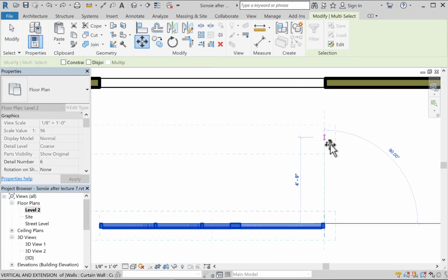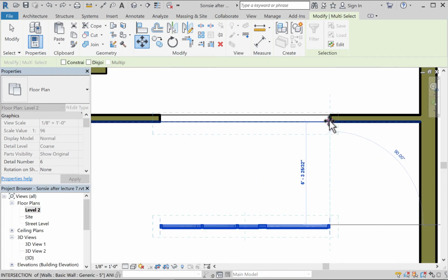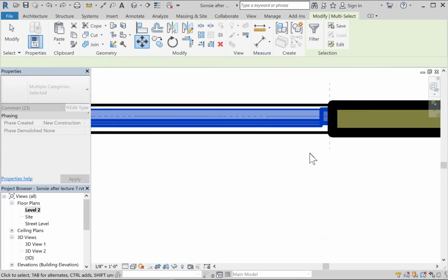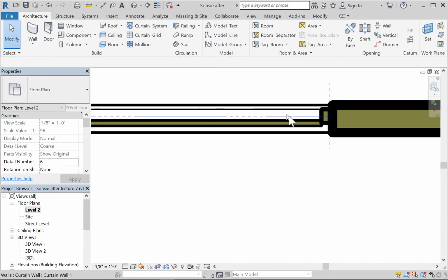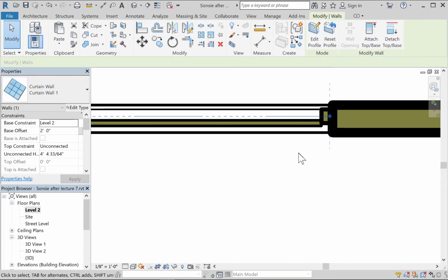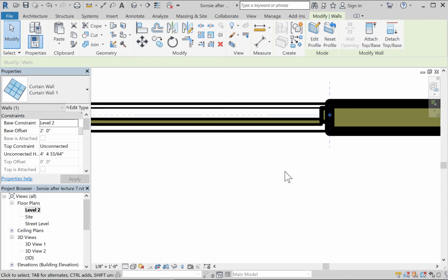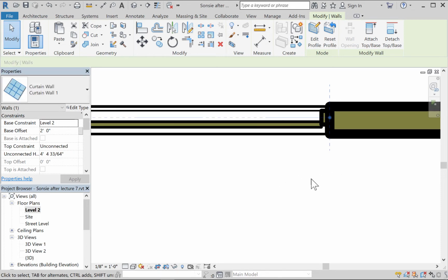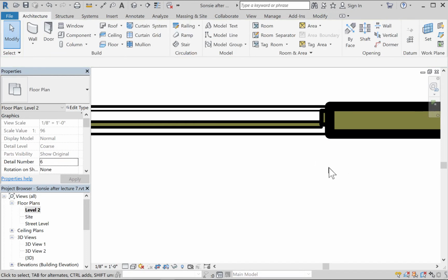And so I need to grab this thing and zoom in on the frame where it's going to go and make sure that I place it inside the wall. The reason is, what Revit likes to do when it has two walls on top of each other, it kind of glues them together. So I'm nudging this. See how the whole kit and caboodle moves? The actual three walls all move together, which is kind of annoying, frankly.